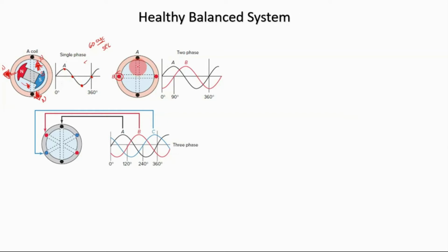So you'll just observe, if this is your magnet, this is your north, and this is your south. At this point, the maximum here is for A, and your B here is at 0. You'll notice that this will go down and this will go up to this point where it is in horizontal location. So your peak now here is at B, and A is at 0, and again it will be on the negative cycle. If you're considering a three-phase system, you just add a coil here.